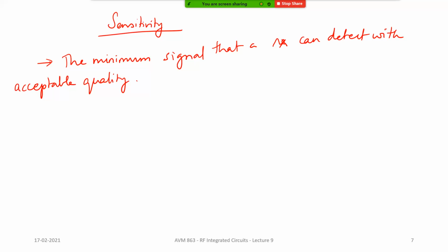It doesn't mean the signal strength has dropped to some absolute zero, okay. There is still some signal, probably the signal available when you have zero tower, like how you sometimes have in your classrooms in IIST, right? Maybe the signal strength is minus 120 dBm, minus 130 dBm or something like that. There's some small signal available, or even let's say minus 100 dBm or something, but the receiver is not able to use that to have any meaningful communication, okay. That's why it shows that you have no tower at all.